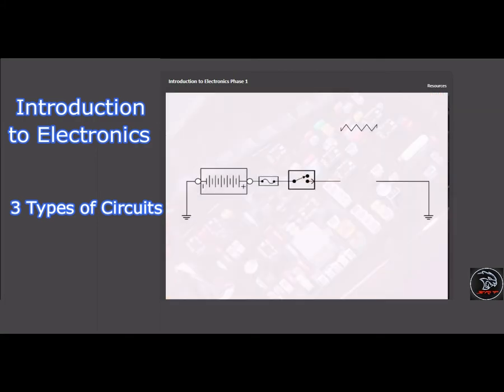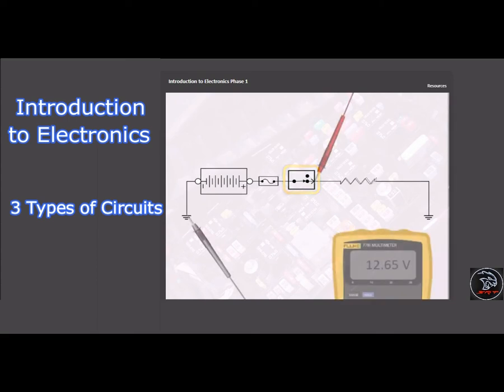In a closed circuit, all connectors and components are connected, and the control device is in the closed or on position. Closed circuit testing is the preferred method for measuring voltage because any unwanted resistance can be identified by a voltage drop in that part of the circuit.